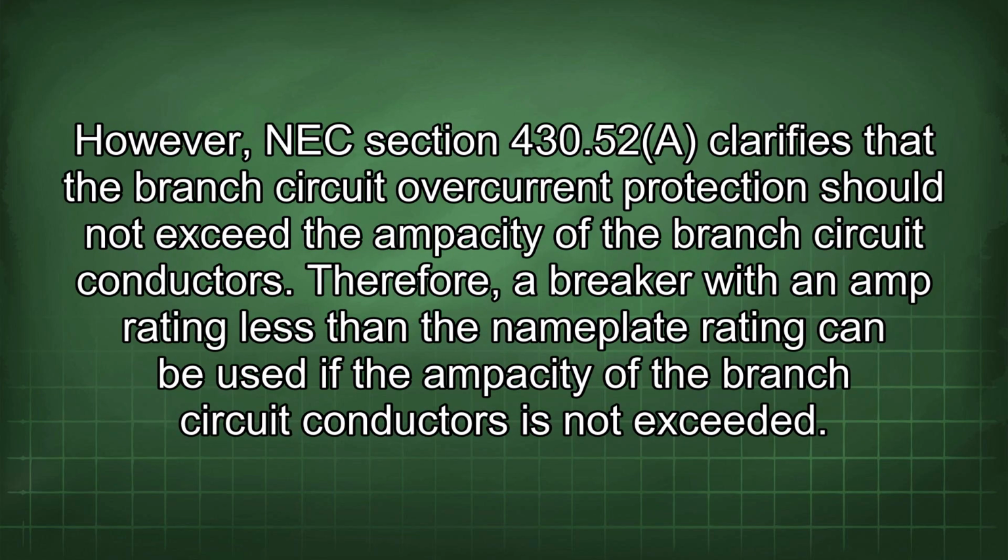However, NEC Section 430.52 clarifies that the branch circuit overcurrent protection should not exceed the ampacity of the branch circuit conductors. Therefore, a breaker with an amp rating less than the nameplate rating can be used if the ampacity of the branch circuit conductors is not exceeded.